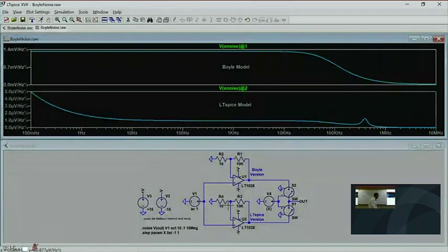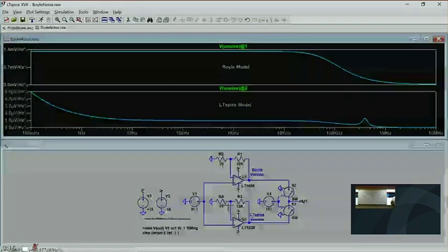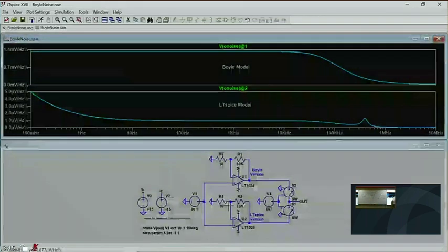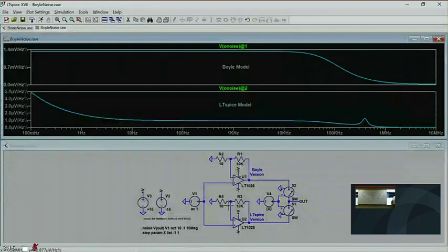So, basically, you can think of this intermediate noise as a voltage source in series with the output. If you put a voltage source in series here, this point will be servoed, because you're sensing this point, looking past that internal noise source, and if you have enough negative feedback, you'll servo out any noise that's in series with that output. But the feedback loop is going open circuit, and that's where you see that noise. What I'm saying is it's an exact noise model.